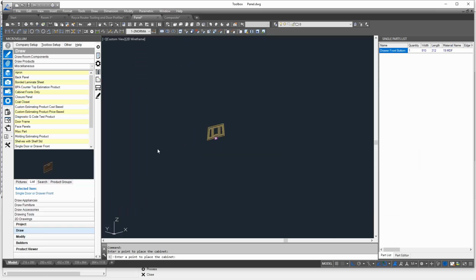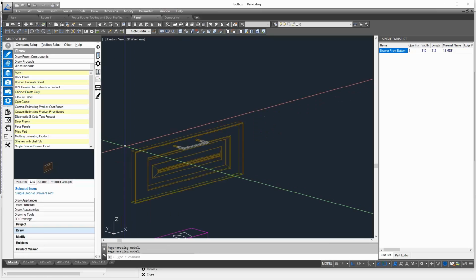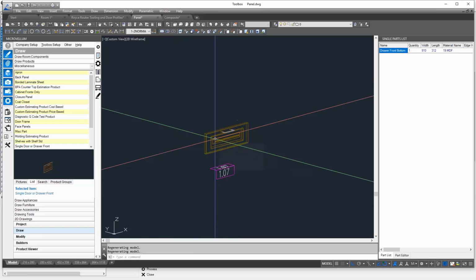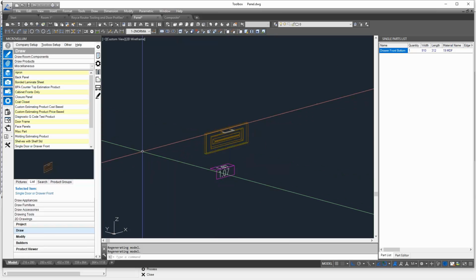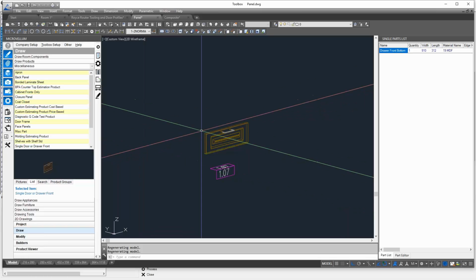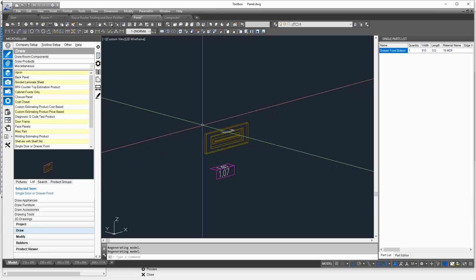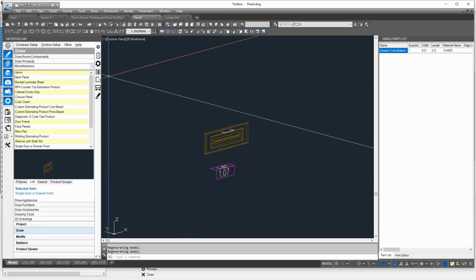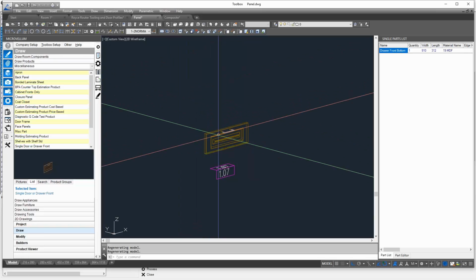One of the things that we have in Microvellum is the ability to import an XLS file. If this was something that you did a lot of, where you're getting a list in Excel of some products that you need to produce, so you have a list of doors that came from a third party, or you're producing them for another company and you have an Excel list, we can set up an import file so that you could basically just import that list.